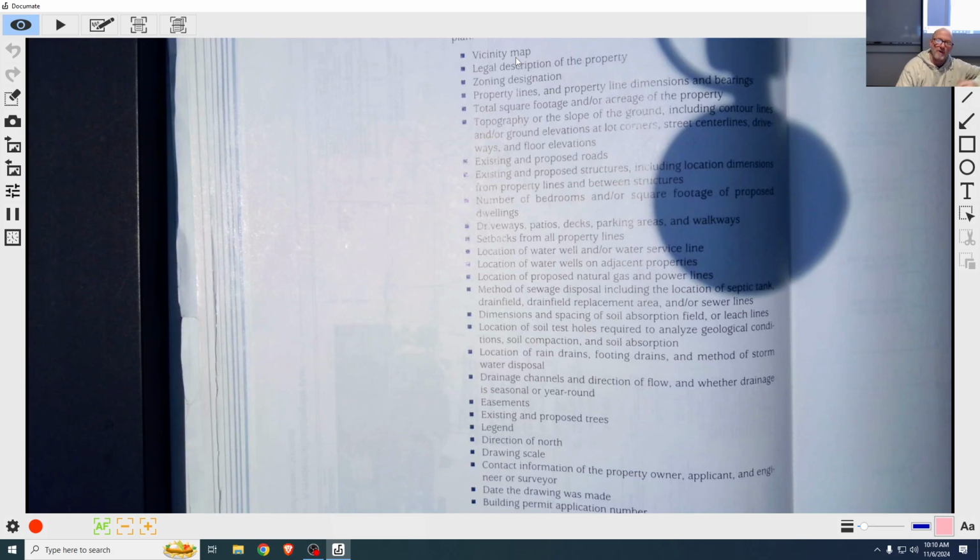Okay, property lines, we know how to draw those, so that's nice. You also include the square footage of the area, the topography, right? Contour lines, spot elevations, and test locations, like where they test the soil. Sometimes that needs to be included. And wherever other things are, such as street center lines, concrete driveways, and parking areas.